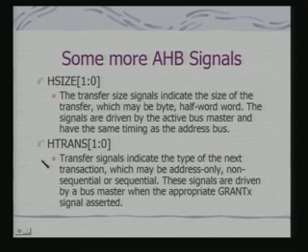Some more AHB signals are size. In fact, this size we have already seen in the context of ARM signals, memory interface signals also, and it is consistent in that context. And HTRANS, these transfer signals indicate the type of next transaction, which may be address only, non-sequential or sequential. These signals are driven by a bus master when the appropriate grant signal is asserted. Okay, so that prepares the devices to expect what kind of transactions would take place next.